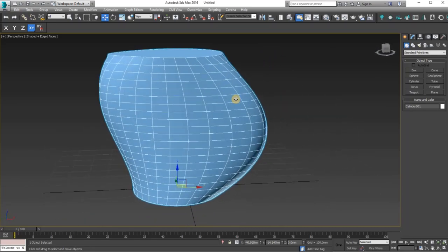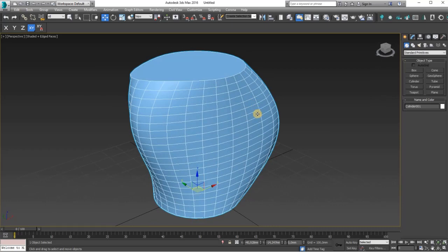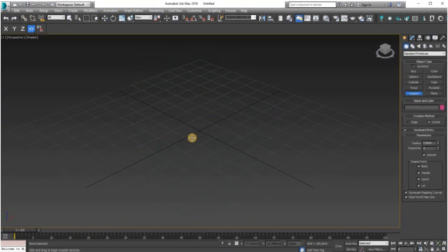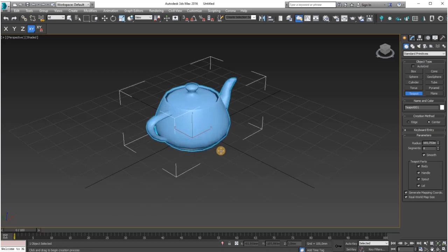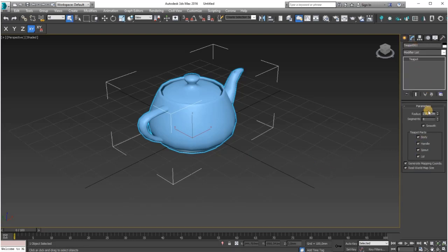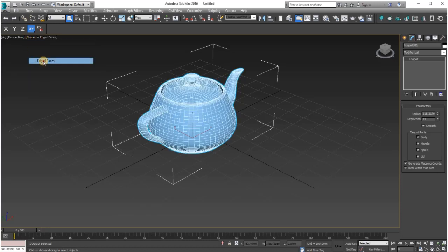Lattice. Select the Lattice sub-object level. The lattice box will be highlighted in the viewport. Next, you can reshape the objects by moving, rotating, or scaling the lattice box. Set Volume. If you select this sub-object level, then the control points of the lattice box will turn green in color. You can select those green control points and move them to fit the shape of the objects without affecting the object.